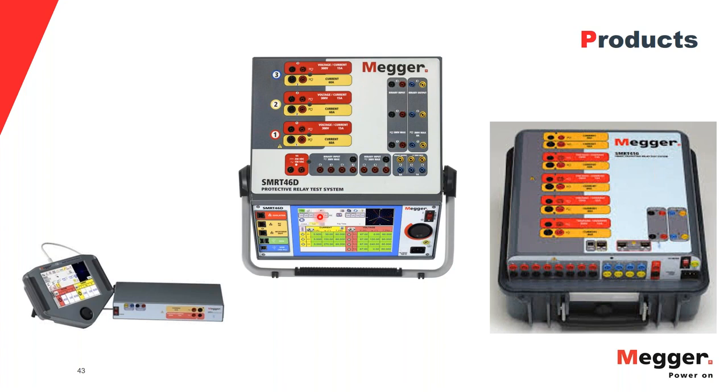The good thing about the D units that we have is whenever you connect the D units with the PC, the software in the PC takes the control, and the onboard display turns into a meter. So you can actually check the metered outputs from your current and voltage. It's always a good practice to see what values the test set is outputting, the magnitude of current, the phase angles. Once you know that, it becomes really easy to troubleshoot some of the testing dilemmas.